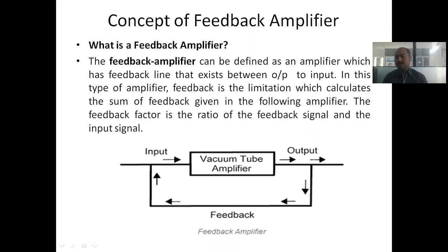In the case of a common emitter amplifier, whatever input is applied, its 180-degree phase shifted output comes across the output of the amplifier, right? Whatever is applied, exactly the opposite comes across the output with amplified gain. So how is it acceptable? For that purpose we have to use another stage, another stage of the same common emitter amplifier, which gives us the output as we applied it, with increased gain. That's why we use the common emitter amplifier.